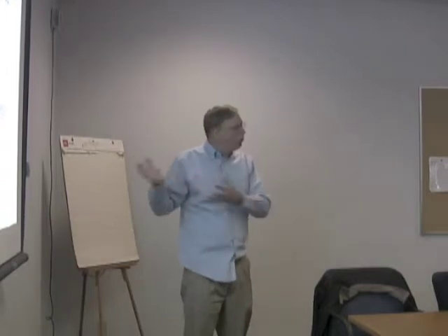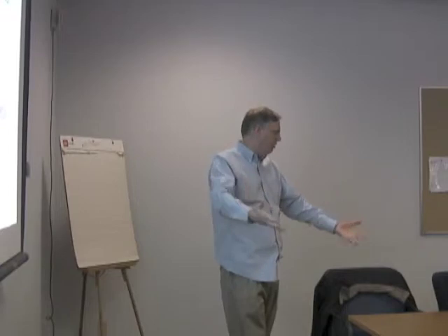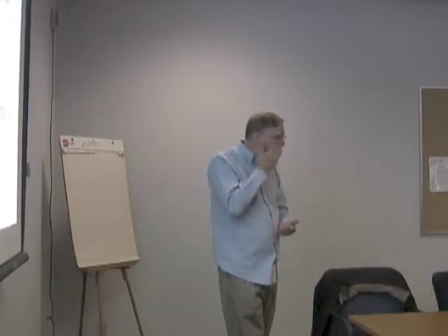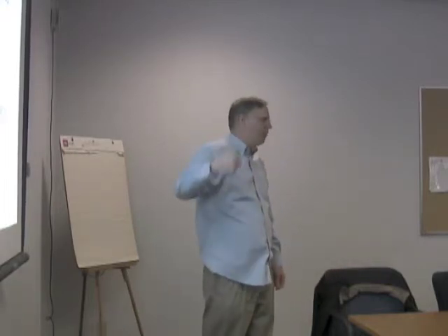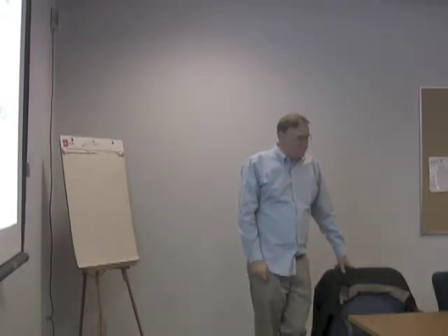The answer was the site effects they were getting were good. The path effects, some were improvements, and in some areas of the model they were actually not working very well. That is, we have to have empirical calibration of this. You can't just say, here's a 3D crustal model, believe my results, and move forward. We were having trouble getting the 3D crustal model simulations to work for any kind of high frequencies. Correct. That's being addressed now. It was getting calibrated at like 3 seconds and longer. Correct, and that's what this check was done, but they can now run them to 5 hertz. So that's been a big step. They're working on getting it to somewhere that's relevant to the problem here.